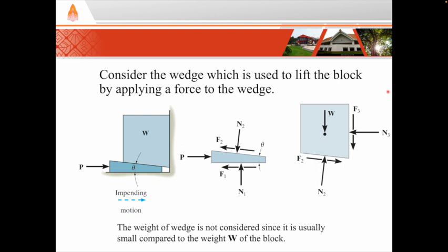And when drawing the corresponding forces, so this friction force and this friction force, for example, it's important to make those forces equal and opposite across the objects. So for the wedge here, this friction force between the wedge and the block points to the left, but the corresponding force, F2, on the block is pointing in the opposite direction to the right.